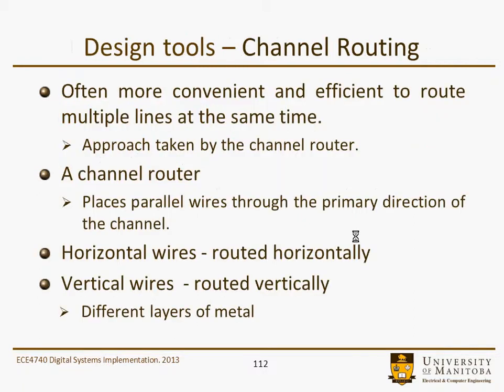With respect to channel routing, again, often it's more convenient to route multiple lines at the same time, and that's an approach that's often taken by a channel router. You place parallel wires through the primary direction of the channel.